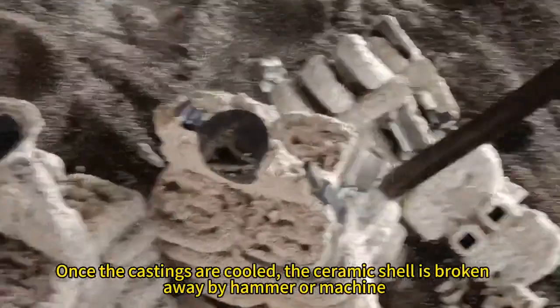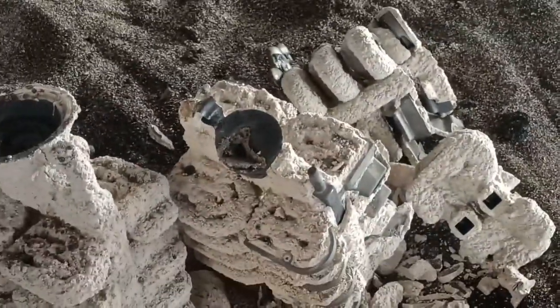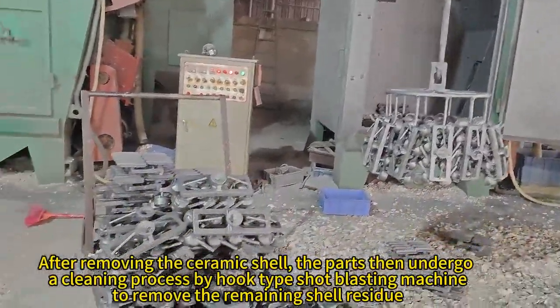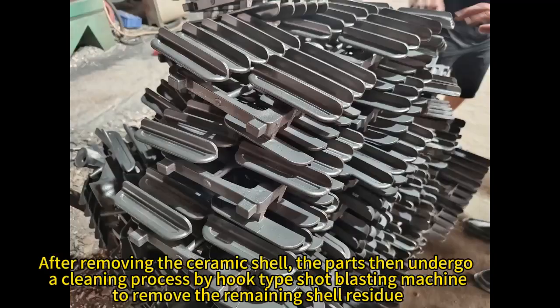Step 10. De-shelling. Once the castings are cooled, the ceramic shell is broken away by hammer or machine. Step 11. Critical cleaning by hook-type shot blasting machine. After removing the ceramic shell, the parts then undergo a cleaning process by hook-type shot blasting machine to remove the remaining shell residue.